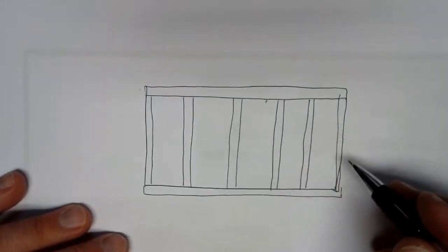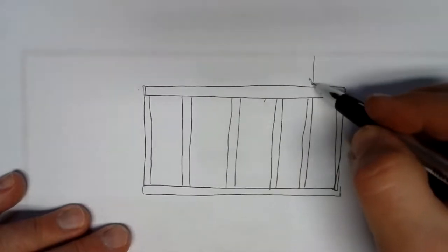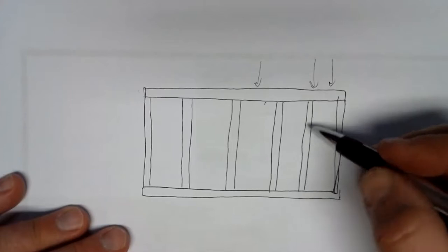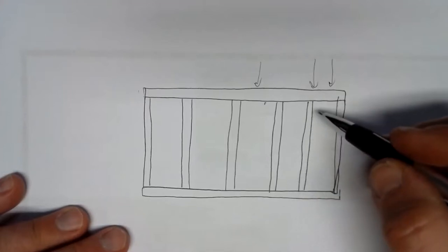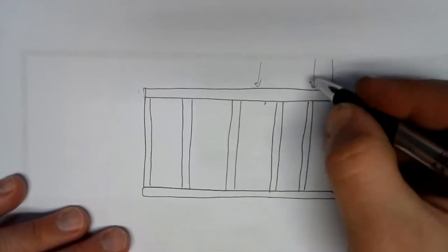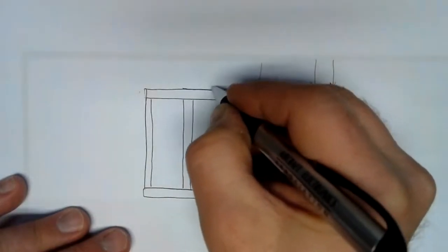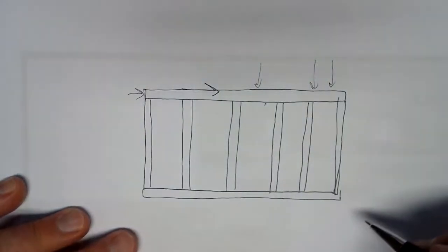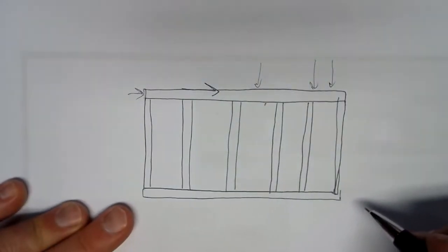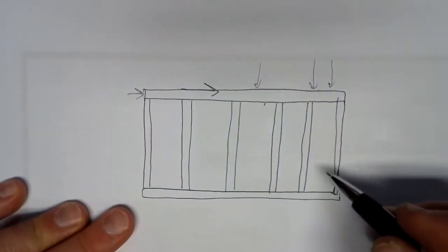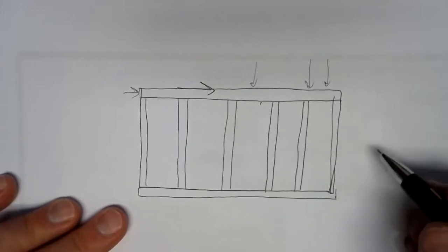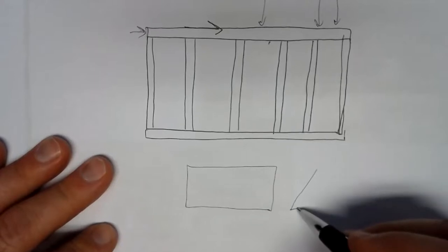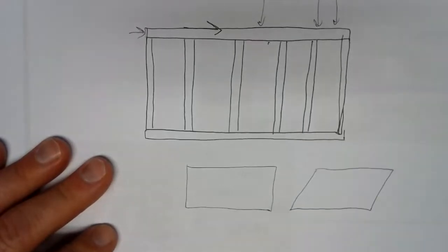Well, if you build one of these things, it's usually because we're putting stuff down on the top. We're putting forces down on the top. That would be a compressive load on these members. But if we're not careful, sometimes we can get loads acting like this. Like if somebody comes in and tries to move this and they push at the top, I think you might be able to visualize what happens to it in a typical wall like this. If you're not careful, it does what we call racking, where instead of being a nice rectangle, it goes to something that looks sort of like that.